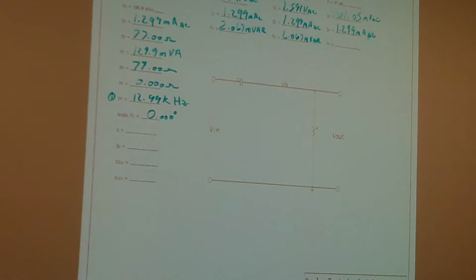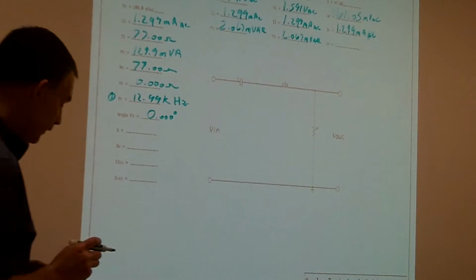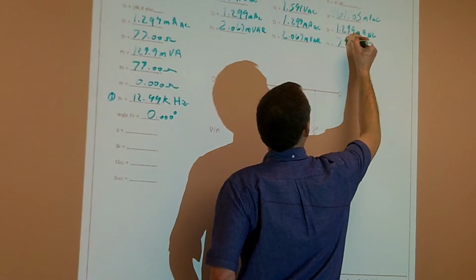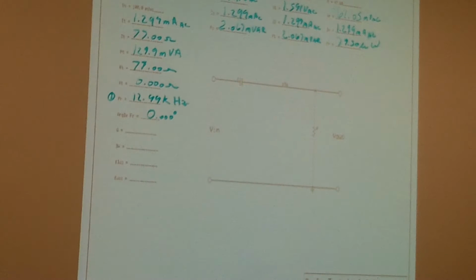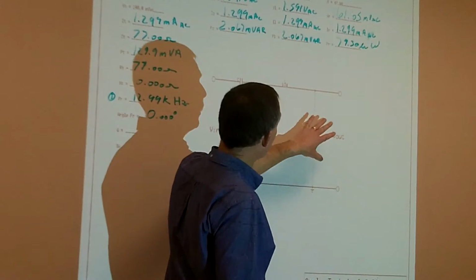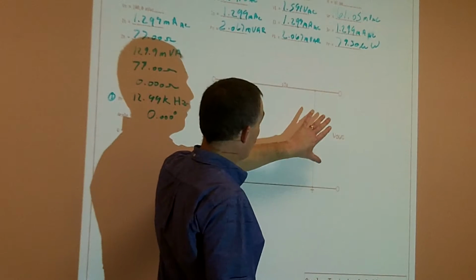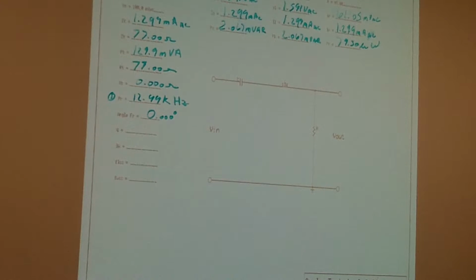Okay. And then the power of our resistor then? 79.30 microwatts. Good. That's true power. That's actually going to dissipate heat as we're going across the resistor, or this resistor could also be an antenna, so that could be 79.30 microwatts as an electromagnetic field. Not necessarily always heat, but it can also be our electromagnetic field.